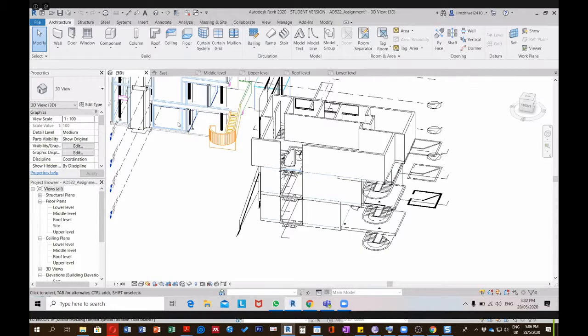So basically, for example, this is the start, and radius. I can change the radius, as you can see. But of course the thickness is big, so I have to select and maybe make it smaller. And maybe I need to drag a little bit like this. It's possible it will not follow exactly the same, because this shape I think is not a normal arc, the one of AutoCAD. That's why it's not following exactly.